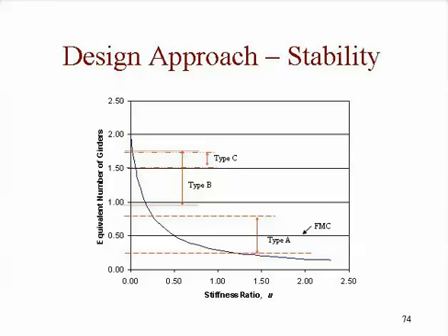So if we're down here, U is very small. That's pretty close to being a fixed connection. If we're in that range, certainly semi-rigid. And the type A approach, which assumed simply that the far end was pinned and the near end was fixed on one girder framing into the column, is right here.